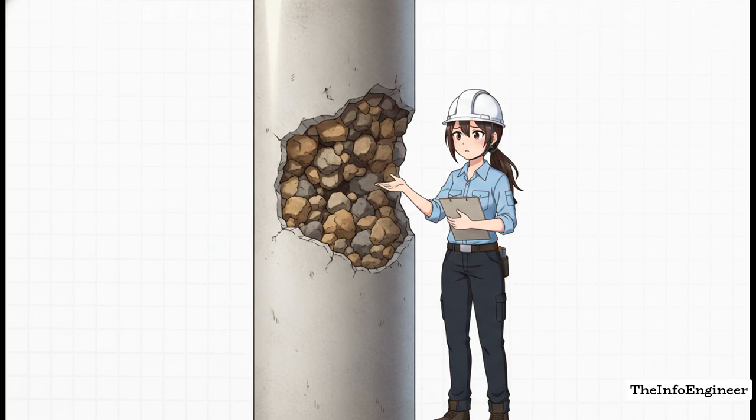There is absolutely nothing worse on site than stripping the formwork and finding a honeycomb staring back at you. It's a severe structural defect where the paste has washed away, leaving the coarse aggregate completely exposed with massive voids. Because the paste and sand are gone, the structural integrity of that entire zone is shot. Tap it with a hammer and it sounds completely hollow. Fixing it means incredibly expensive, time-consuming post-pour repairs, like structural patching or grouting, just to restore the element's basic load-bearing capacity.